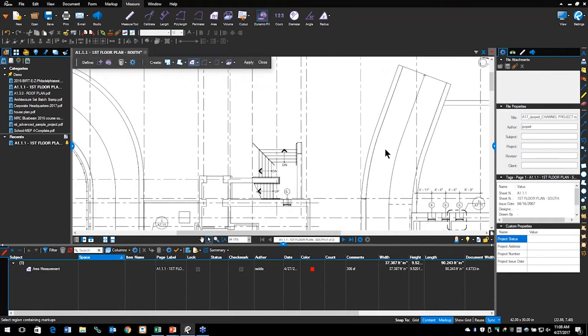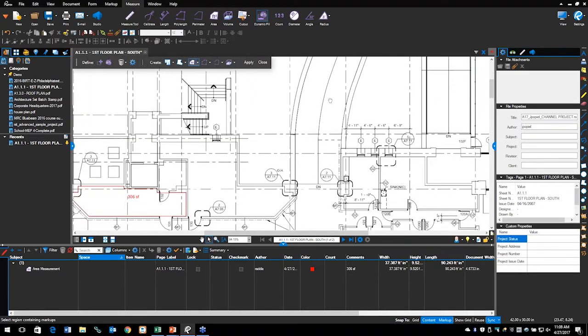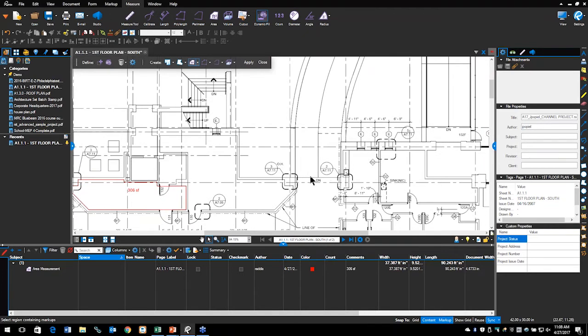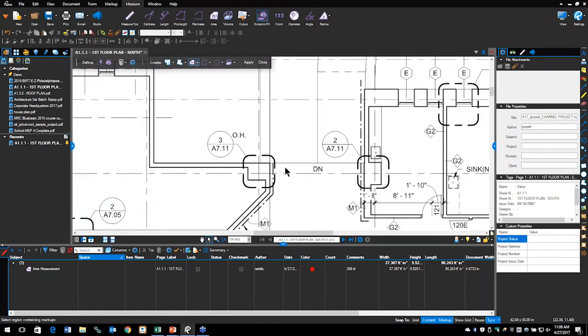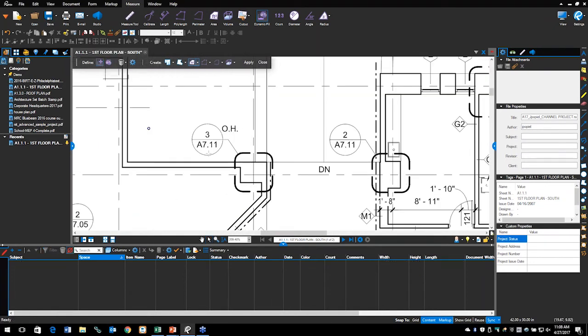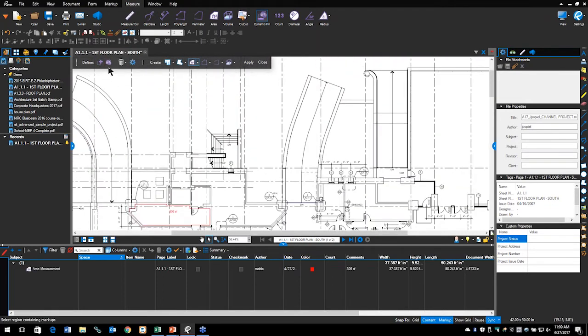But let's take a look at, let's say, a boundary like this ramp here. So the ramp has an edge across there, maybe not one across there, but I'm going to just go ahead and make sure that it actually closes off at the bottom here. So I'm going to add a line across here at the bottom. And let's see if I can't get that line to go in. Let me try that again. Single click here, and then I will double click there. There we go. Okay, so let's try the dynamic fill in that particular area.